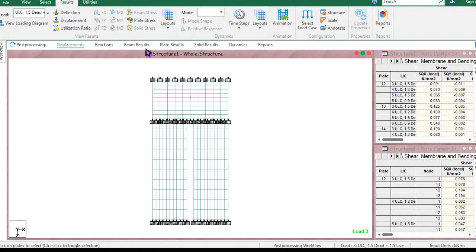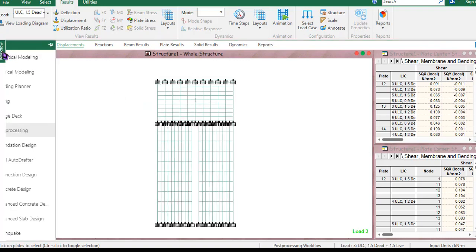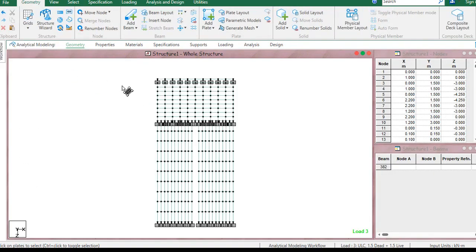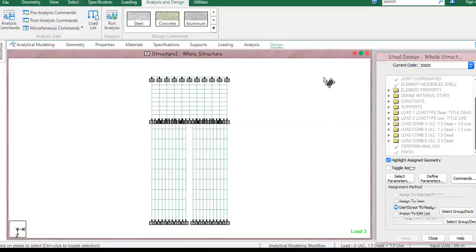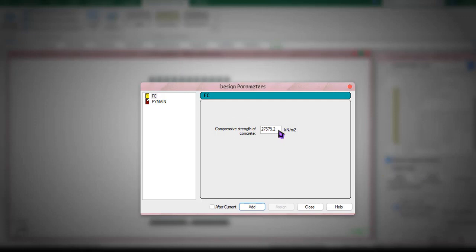Now the design of this slab. It comes to be just getting into the analytical model here. I can design it as a concrete slab. I just select the parameters. I'm picking the grade of concrete, just the grade and stress, and Fy for rebar, and defining the parameters. I'm not really a fan of using kilonewton per meter square as the base value.